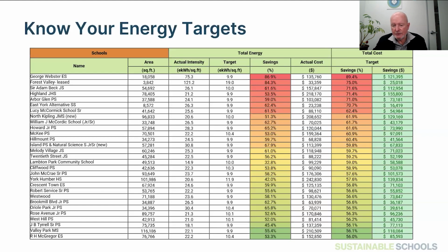But going into any individual school for one of these projects, the starting point is how much room do we have for efficiency, and at least handling energy efficiency in parallel with the development of the heat pump projects. So every school has a rational target which dictates how much energy and emissions it can save. And by getting that efficiency right as you're doing or preparing for an air source heat pump project, it gives you a lot of flexibility around the cost, the operation and the economics of the heat pump installation. Next slide, please.